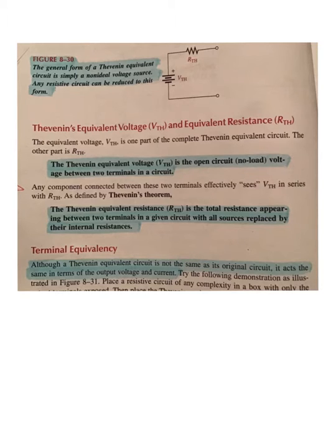This looks like a chapter 3 problem with one resistor, one power supply. That is what a Thevenin series circuit looks like. The reason why Thevenin's is such a great theorem for difficult problems that must be repeated multiple times is because the final circuit literally boils down to a battery and a resistor, or an impedance in later chapters. So keep in mind what that looks like.